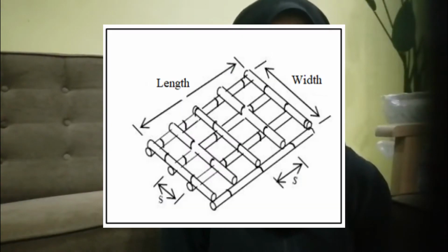However, nowadays many researchers use bamboo foundation for soil improvement on soft soil. For example, bamboo piles are used to stabilize soft soils and reduce building settlement, and according to Marto, bamboo can distribute embankment load uniformly. The bamboo laid in a square position forms an interlock or pocket that creates an increased stiffness of bamboo, which distributes vertical pressure evenly and could minimize differential settlements. This figure shows the bamboo in a square pattern.